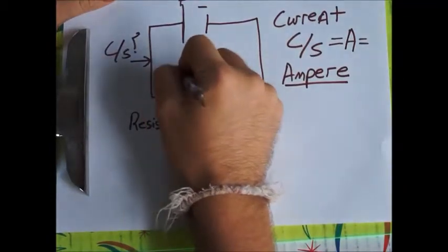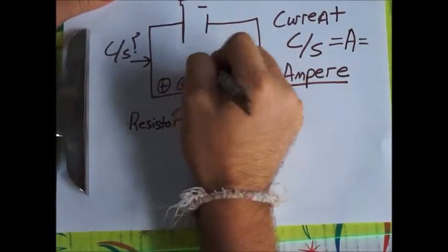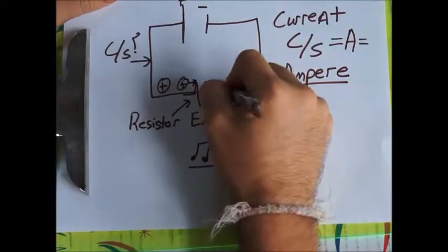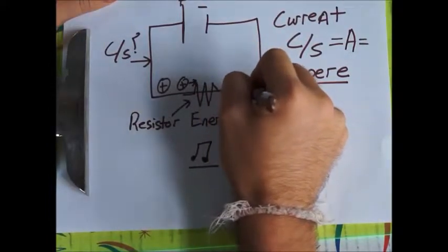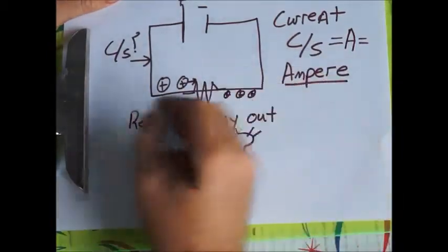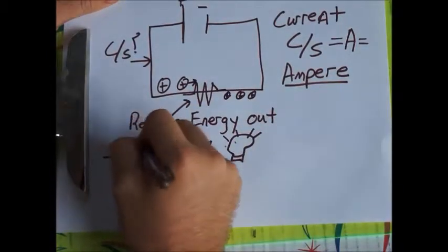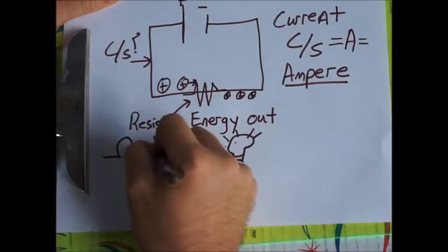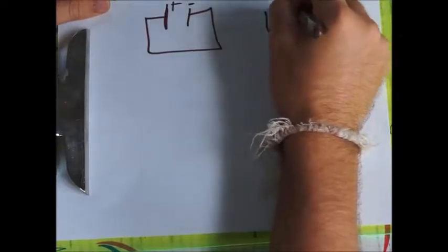We have to have resistance in the circuit in order to harvest the potential energy that's imparted upon the charge carriers by the battery. Resistance is measured in units of ohms. An ohm has subunits of volts per ampere. So let's put all this together so we can do some deeper analysis of circuits. So I want to introduce an equation. V, which is voltage, equals I, which is the symbol for current in amperes, times resistance, which will be in ohms, which has subunits of volts per ampere.